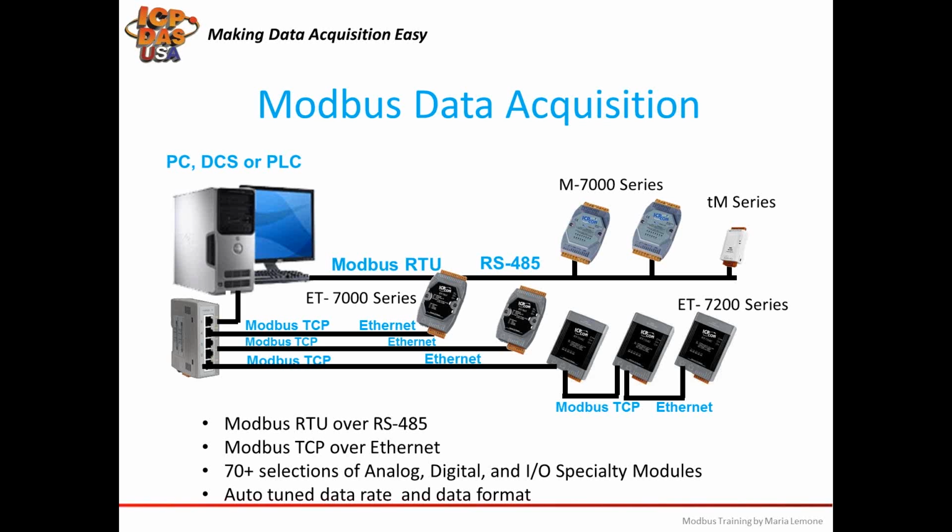Modbus RTU-based equipment communicates over RS-485, which communicates over two copper wires that are usually twisted around each other. Modbus RTU supports communication distances up to 1,200 meters or 4,000 feet without a repeater. Greater distances can be achieved with a repeater. There are different speeds at which Modbus RTU devices can communicate, like between 1,200 and 115,200 bits per second.